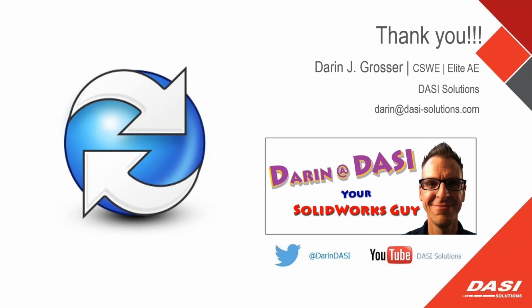Duplicate file names. Can you overwrite the file over itself, keeping the existing version, or do you have to choose which part you keep? So when you have files that are checked in, as long as you have them checked out, which typically when we're dealing with setting up a vault in the beginning, you want to be the admin, which is the super user permissions. You can pretty much do anything that you need to get the vault set. When you have a file that's in the vault and you try to copy another file of the same name in it, permissions would allow you to overwrite previous version.